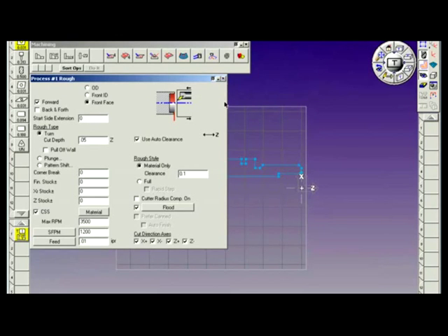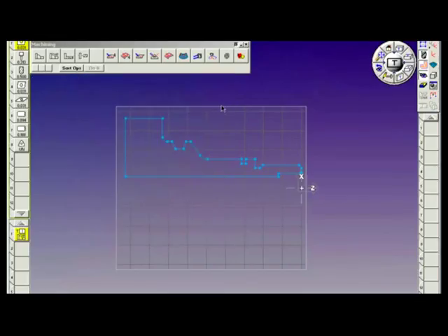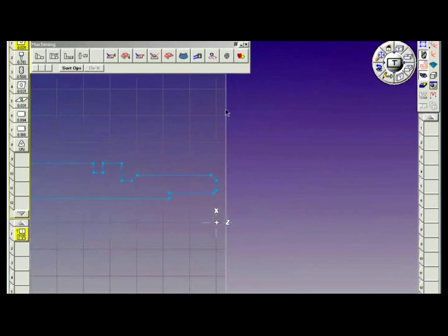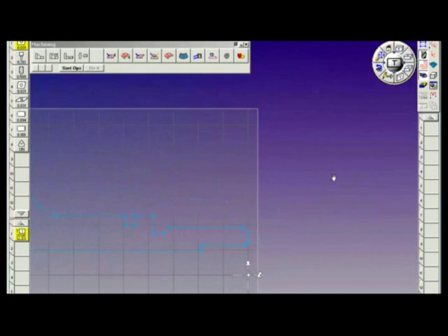Go ahead and close the process tile. The process tile can be closed by clicking on the X here, or a simple Control W, which is equivalent to a close window command, will also close the window. We're going to machine 100 thousandths off the face of this part. I'm going to go to top view, make sure that I'm flat on the screen, and zoom up in this area and select the face as my start feature.